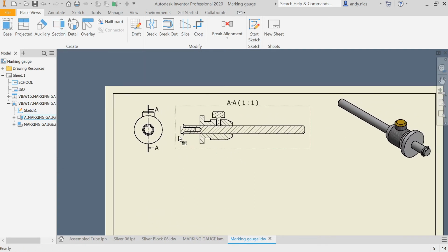So we've got our labels here, which we can now move a bit further to get them away from the geometry. If I'd selected right on the edge, these would be locked, and in fact the labels would be within the shape. So make sure you do the way I showed you there. If you want to change any of this, I'm going to move this underneath and change the name of this view. Don't delete it and replace it with text.